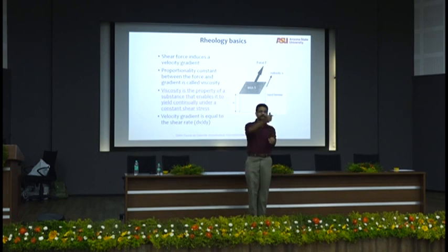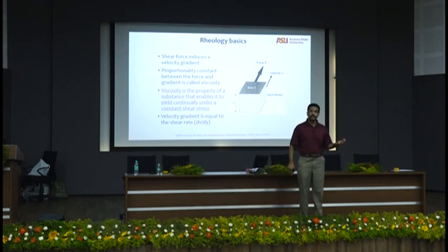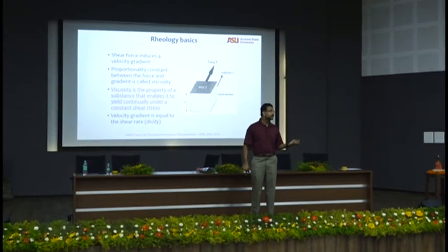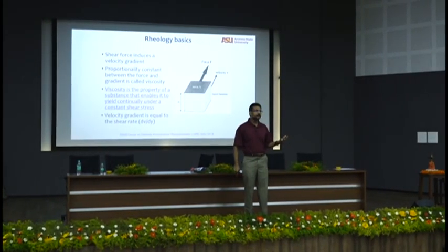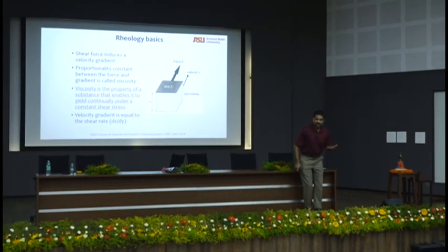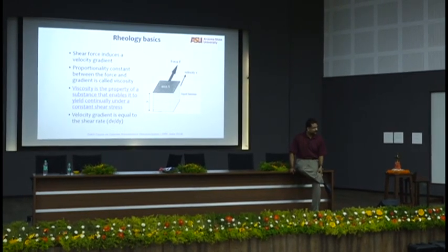When you pull a piece of steel, you draw the stress strain curve of steel. You get to a point where the linear portion ends and the curve starts to deform. You call it the yield point. Why are you calling it the yield point? What is yielding? From an elastic material, you start plastic deformation.